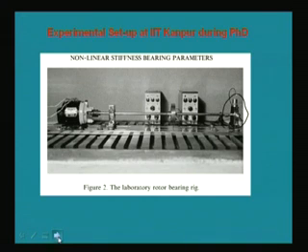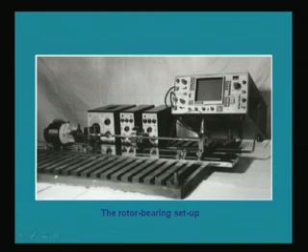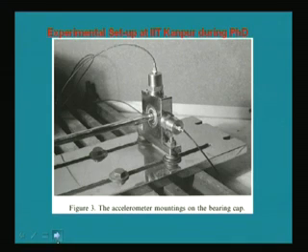Here we can see more closely. We can measure the vibration of the bearing using these accelerometers, and we can analyze those to find the condition of the bearing.